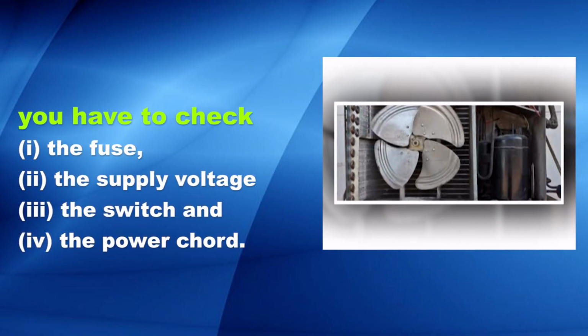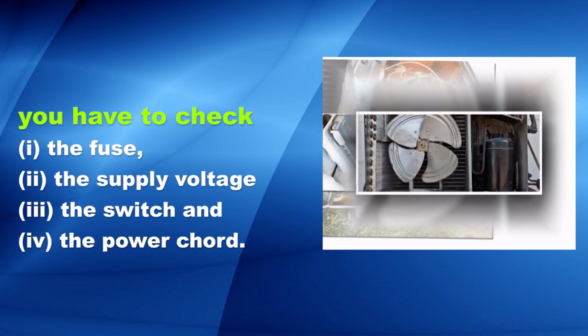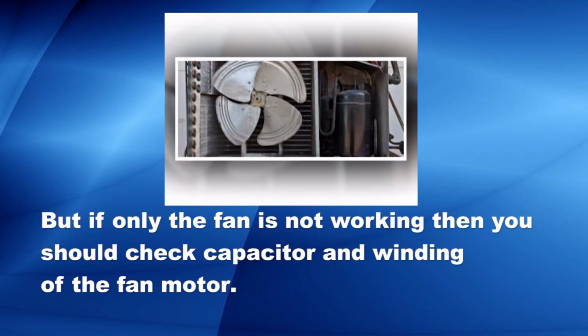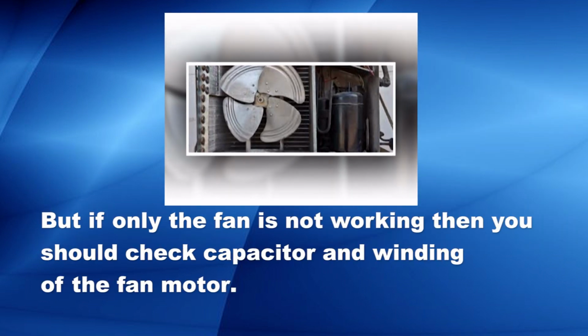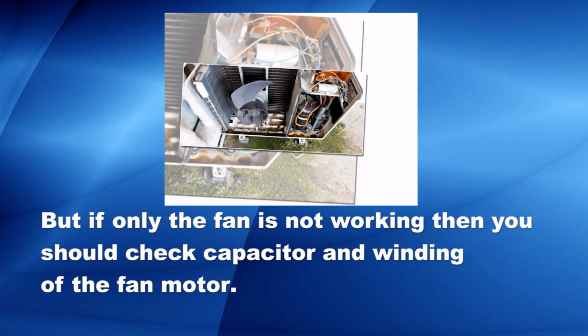So you have to check the fuse first, then the supply voltage, then the switch and the power cord. But if only the fan is not working, then you should check the capacitor and winding of the fan motor. If found to be defective, then the concerned part, that is the capacitor, is to be changed or winding is